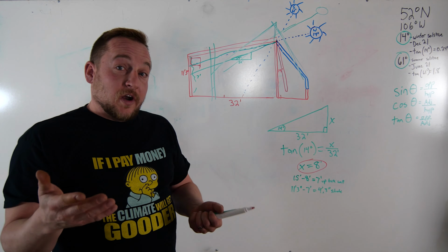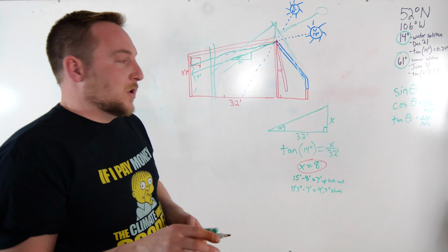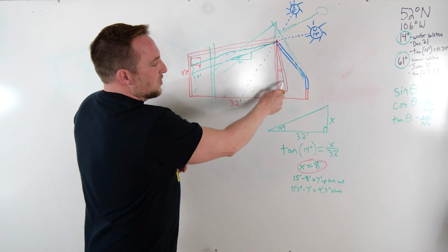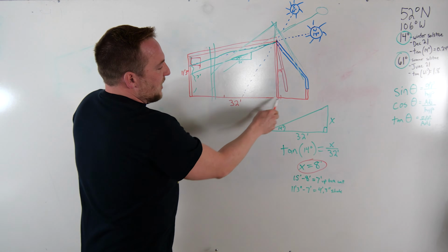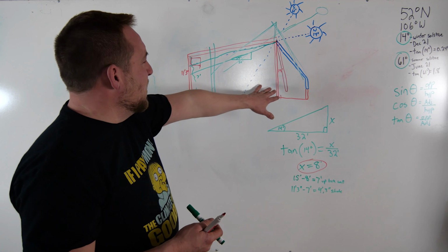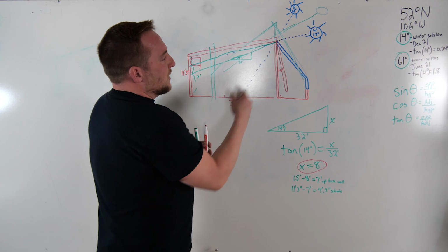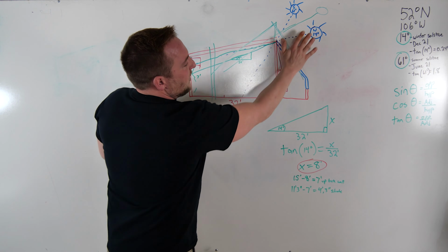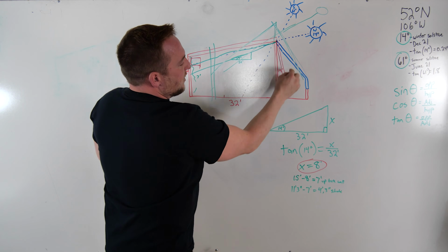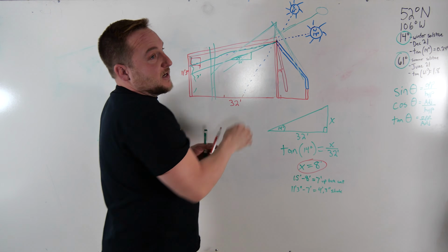Now, if you just want a greenhouse, and you're not going to use it at all in the summertime, just the wintertime, you would do it like this. So you'd have way less full sun in the summertime, but it would just be winter use. So this would mean less heat loss, because heat rises here, and slightly less surface area of the glazing for heat to lose.